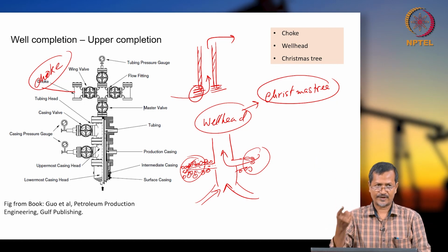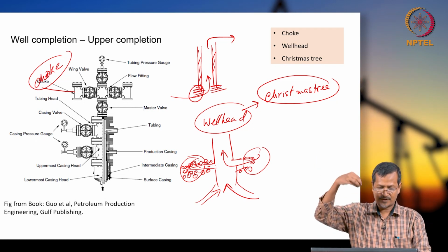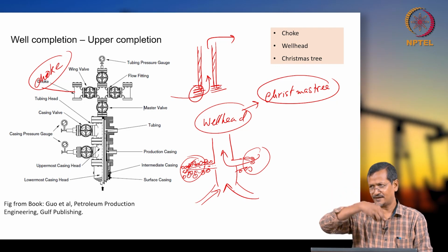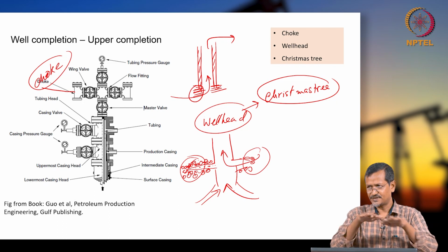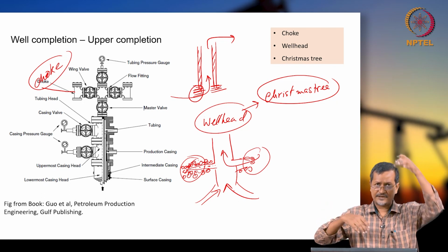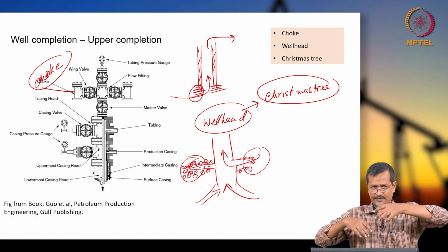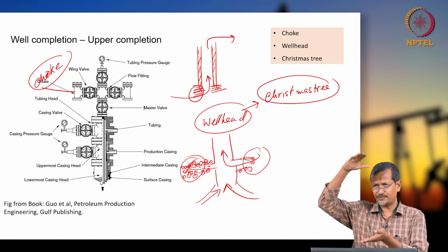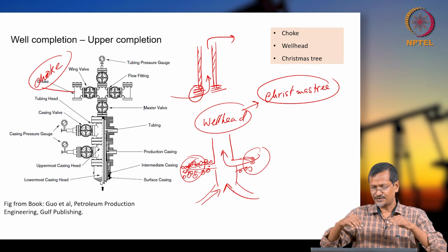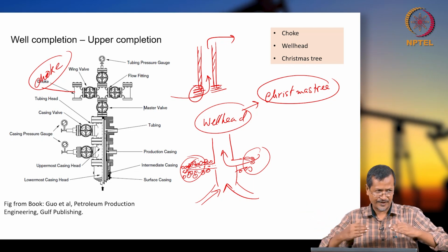When it is not coming out to the surface, at that time you can do any piping cleaning, or you can put in any artificial lift system. The reservoir has a certain pressure, let's say 100. You create a column of high density fluid, H rho g, and if you have H rho g, you can create the same pressure as the reservoir. So in that case, reservoir fluid will not be able to enter the wellbore.